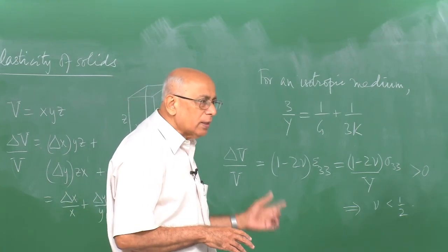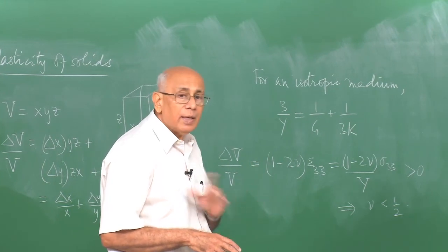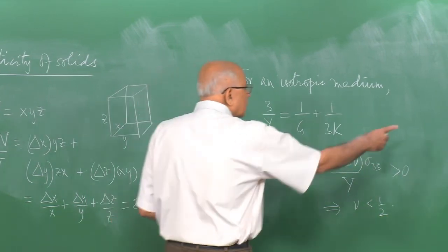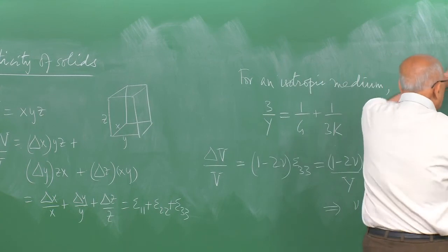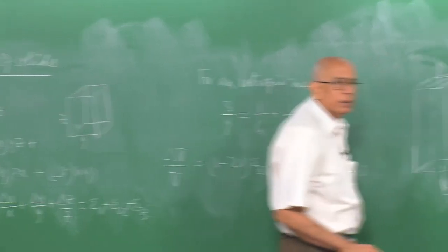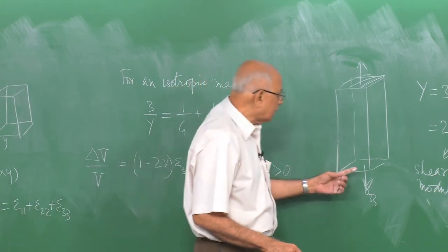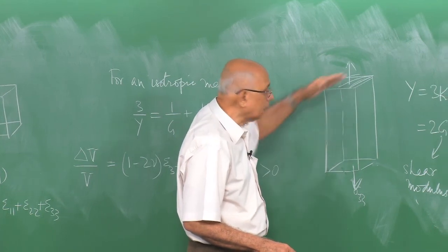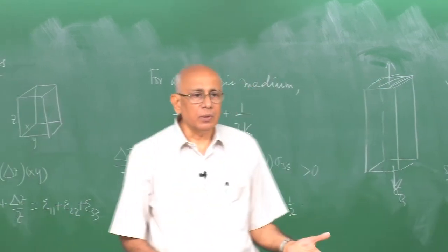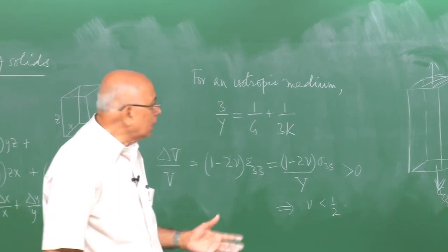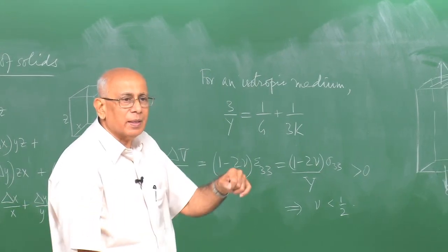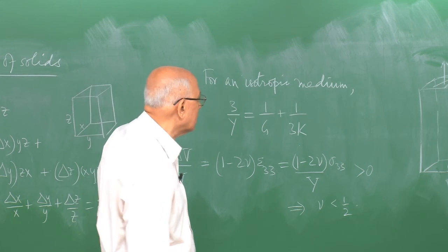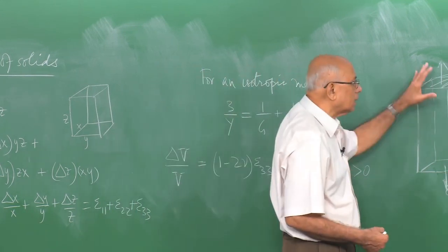By the way, even elastic deformation is not instantaneous. Nothing can be instantaneous. It's very fast compared to the time scales you are interested in. If you take a thing like this and you clamp this end and you apply a load on this end, that's applying uniaxial tension, the stress has to propagate from here to the rest of the medium, all the way here, and it cannot do so faster than the speed of sound in the medium. And that might happen in milliseconds for normal laboratory conditions. So you think it's instantaneous response, but actually it is not instantaneous in the technical sense of the word, but for all practical purposes it is instantaneous.